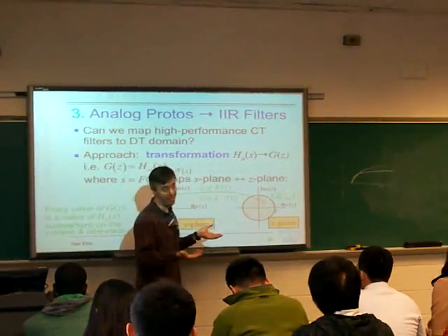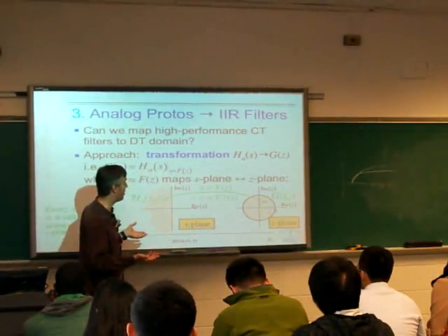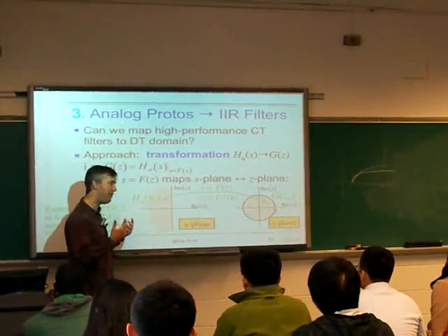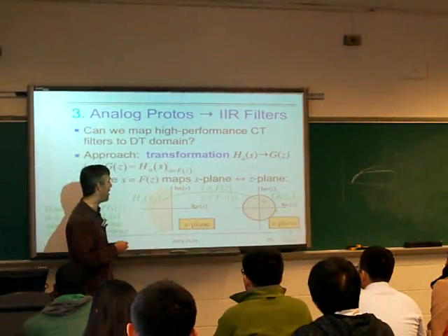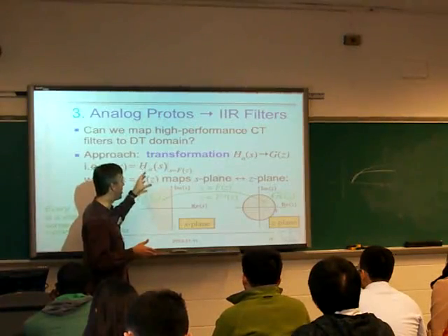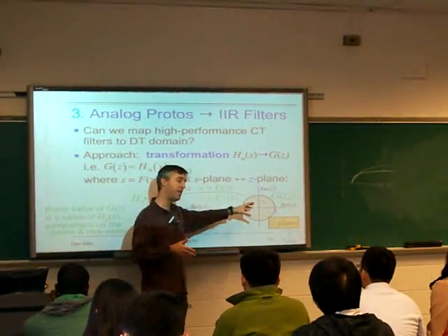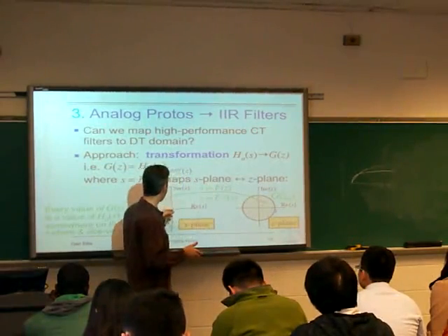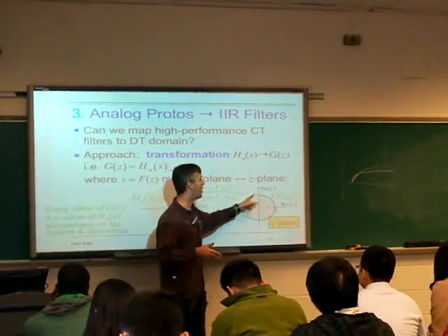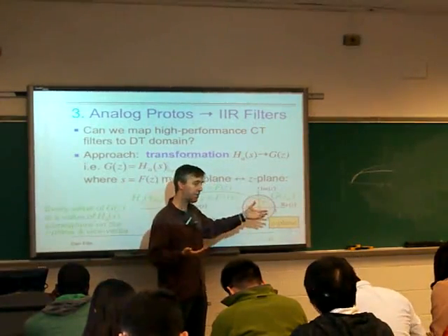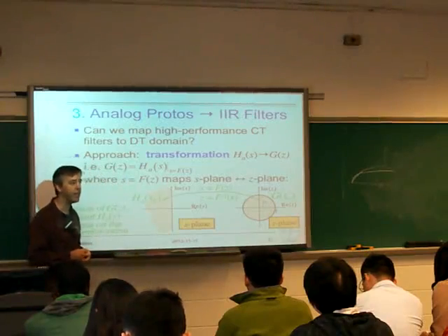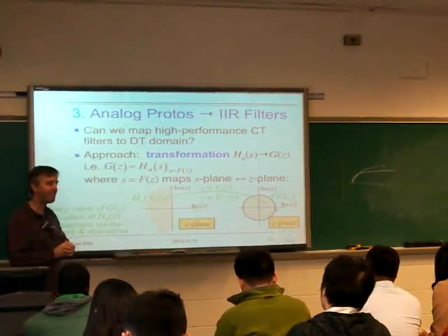That's not that difficult to come up with. The clever part is, once you do that, if you give me a polynomial G(s), then I know what its G(z) is going to do. And if I've controlled the values on the imaginary axis for G(s), then I've got the same controls on the frequency response, the unit circle, for G(z). But we'll talk about that on Monday. Any questions? All right, see you Monday.